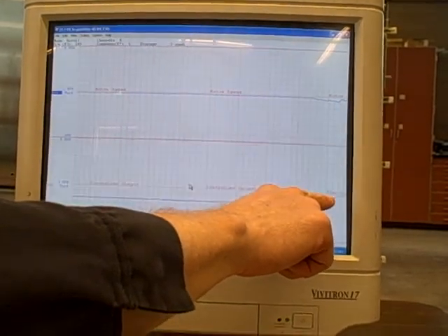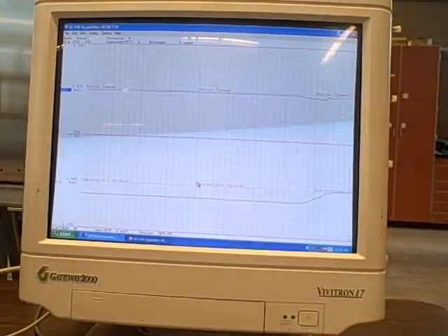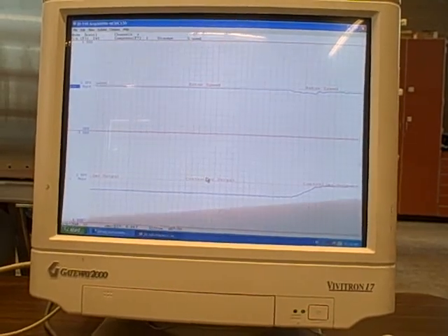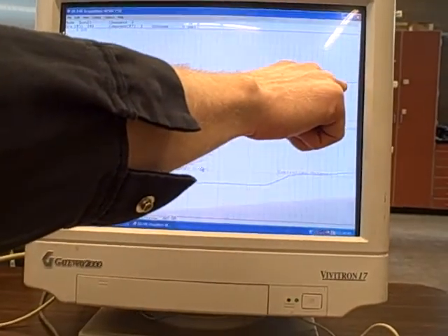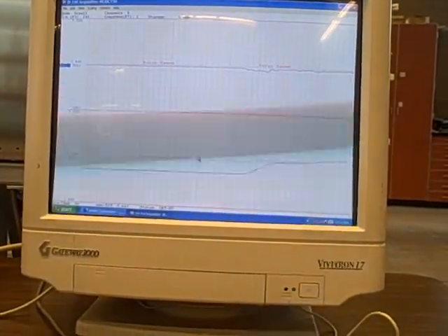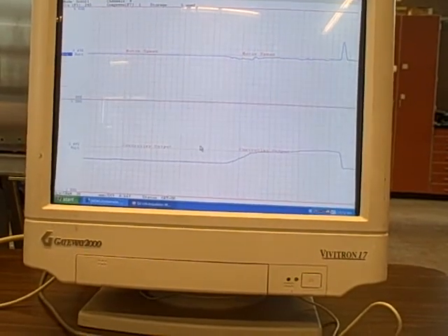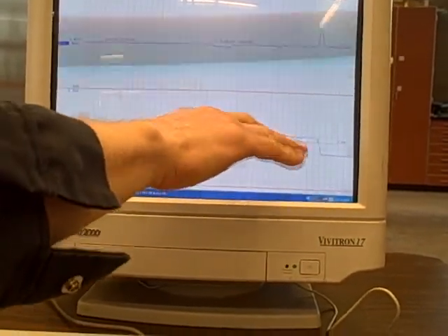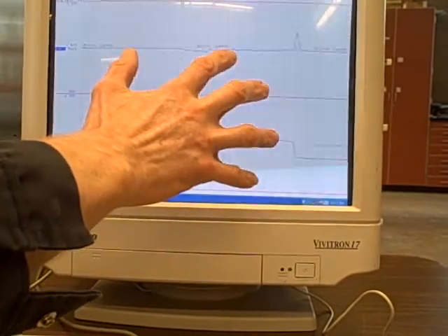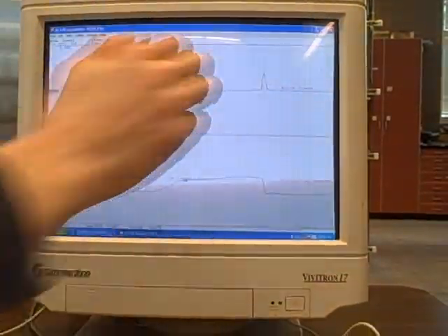Now, focusing back on the screen, as I slow down my motor, it aggressively ramps up the power to the motor and does all it can to hold it at speed. I almost can't get this thing to slow down more than 1 square on the screen. If I let go, it overshoots because of all the output that got built up during the integral wind-up period. When I let go of the motor shaft, it briefly oversped, then corrected itself.